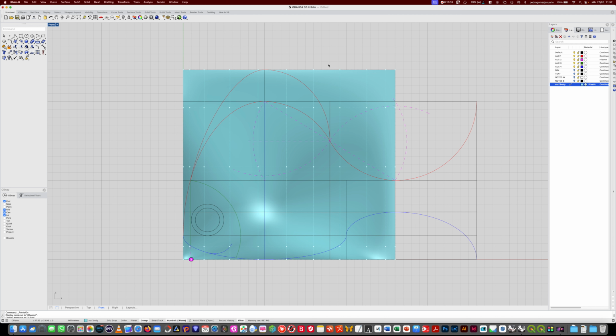So I will start with the lower one. Now, if I try to move this down, this will be below these two. So I need first of all to select these points and move them down. For that I'm going to use the grid snap. So I will move every point. Okay, now I can take off grid snap. I can move slightly up to be more or less according to this one.